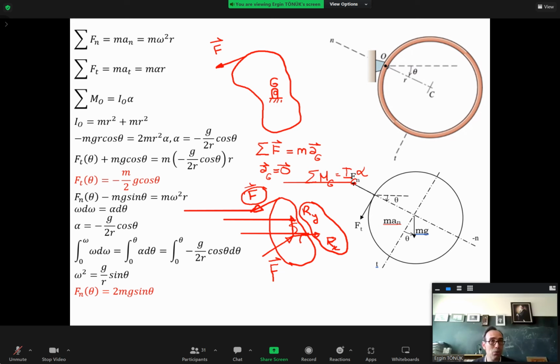So the sum of the forces should be equal to zero. And the best part is, because that is zero, if a body is rotating about its mass center, it's not going to shake its foundation like the vibration mode of your cell phone. It's like a well-balanced wheel of a car. Why do you balance the wheel of the car? To drive smoothly.